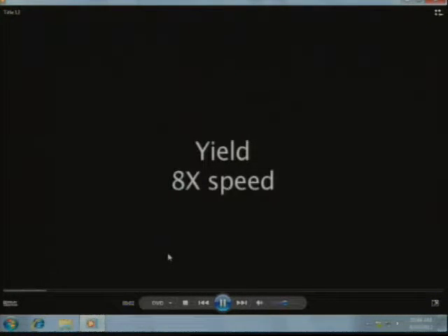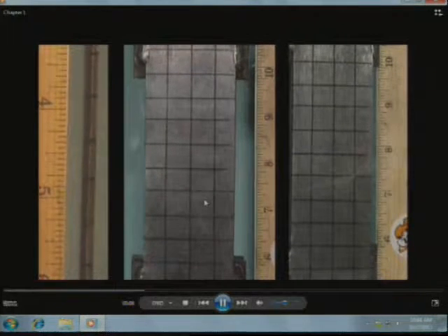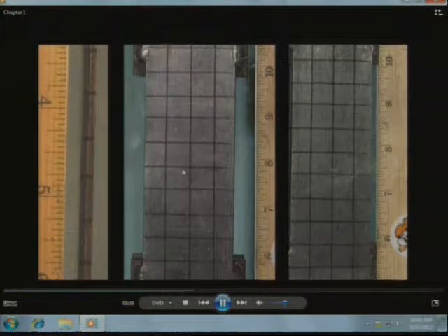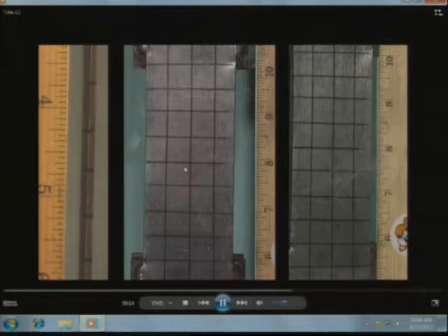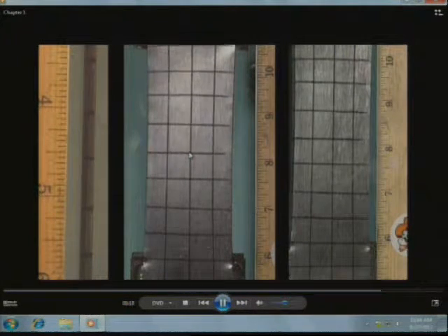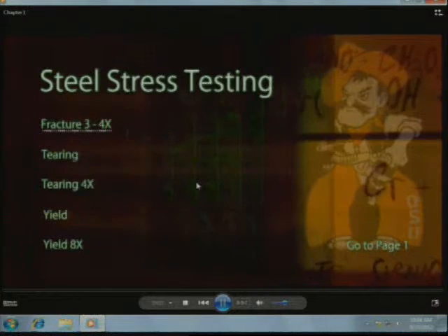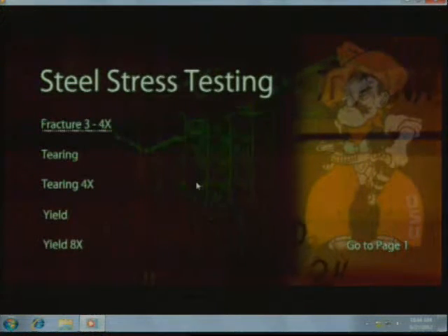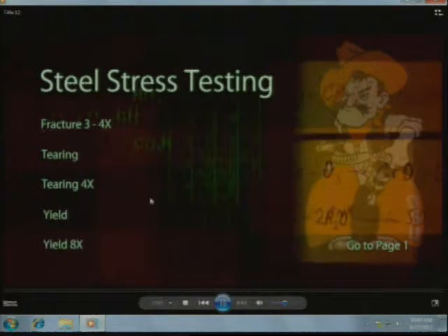And if we talk about the rate of movement over this test, it's loading at a constant rate, and the squares are not really changing in size, are they? We're pushing at a constant rate. Then all of a sudden, oh, it's going faster. Whoa. That's what it would feel like if you were riding on that structure, right? It's elongating a little bit more, then, oh my! You feel like you're going to fall off the edge of a cliff. You with me? Okay, well, there's yielding.